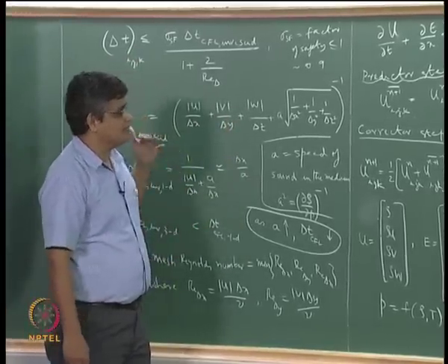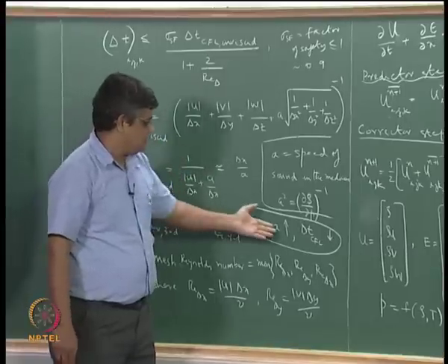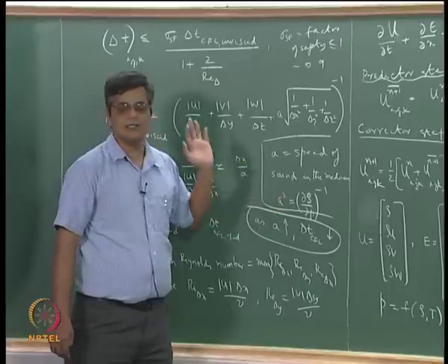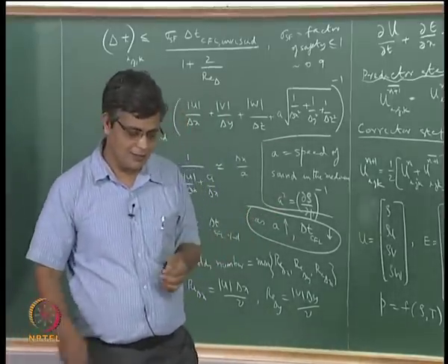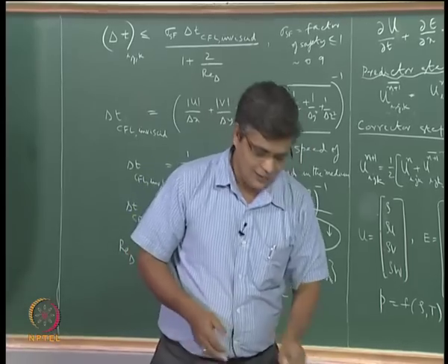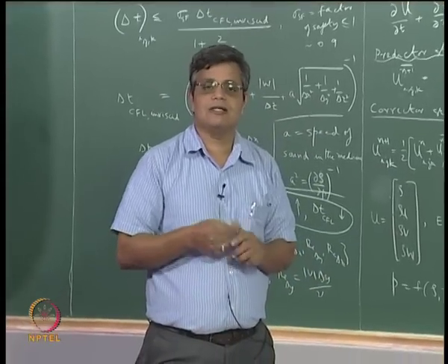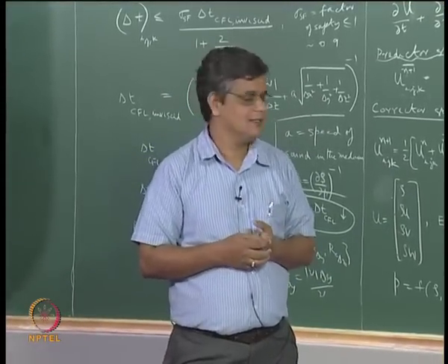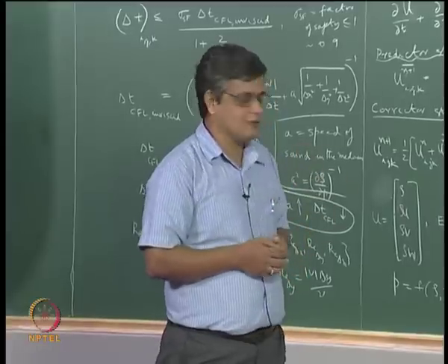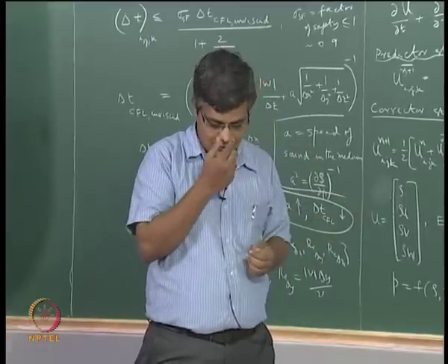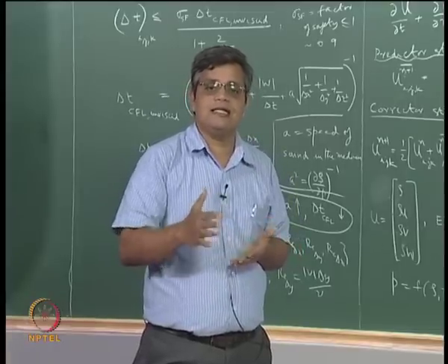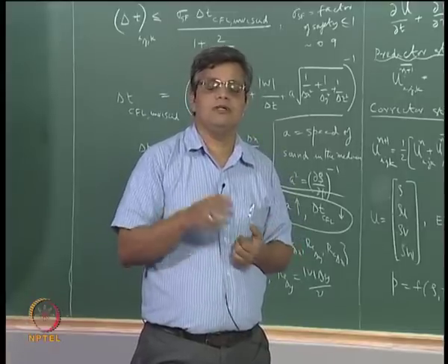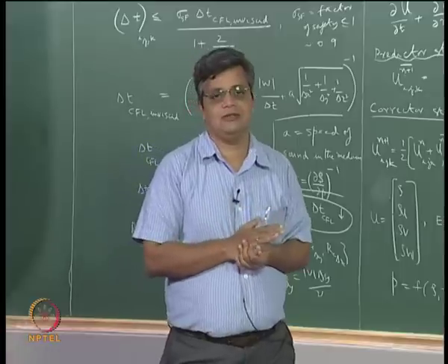Okay. And in the incompressible limit, A is infinity, so that means that this method will not work. Okay. So the explicit method, which typically has a constraint, a Courant number type of constraint, and in the case of viscous flows we have additional constraints, cannot be directly applied to incompressible flows because of the stability requirement.